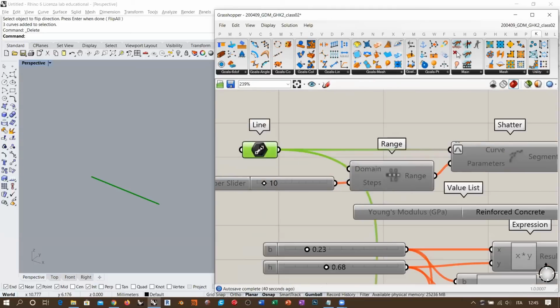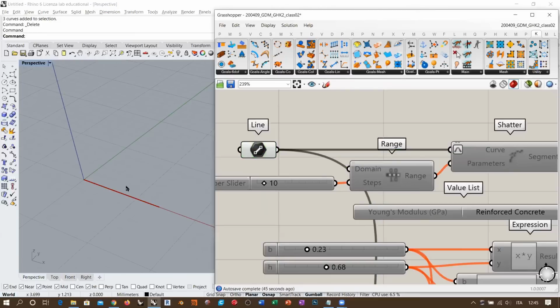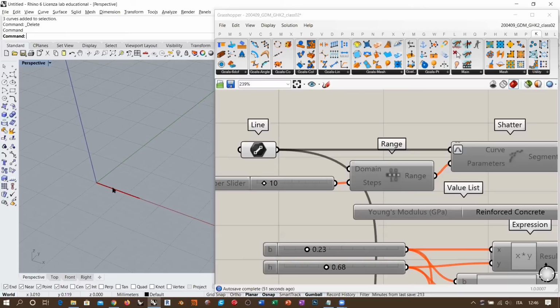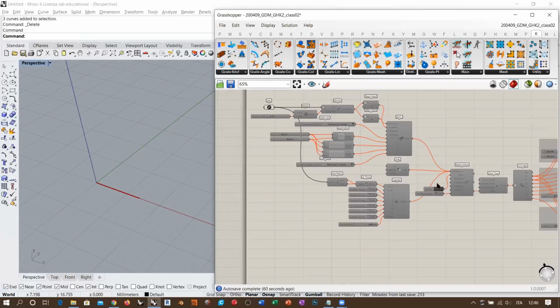Okay, so let's say we have this beam here. Now, strategically, this beam was oriented like the x-axis. Okay, but the fact is that it is not oriented as an axis from the coordinate system. Because even if I change, for example, the orientation of this beam and I place it along the y-axis, we can no longer work with the actual support, okay? Because things will tend to work in a weird way.